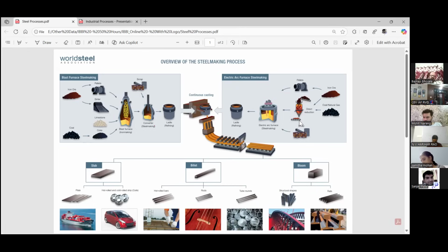From the kiln, we get clinker, or sponge iron. The sponge iron is further fed to the electric arc furnace. In the electric arc furnace, electrodes are immersed, and a high intensity electric arc passes. Again, due to the high intensity of the electricity, your iron, or sponge iron, will melt down and convert to liquid iron.